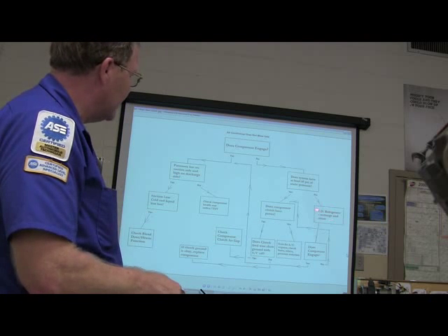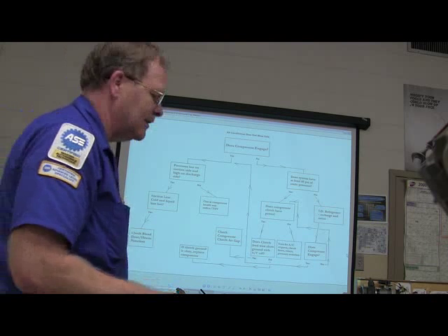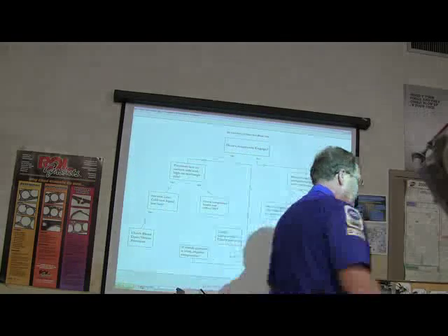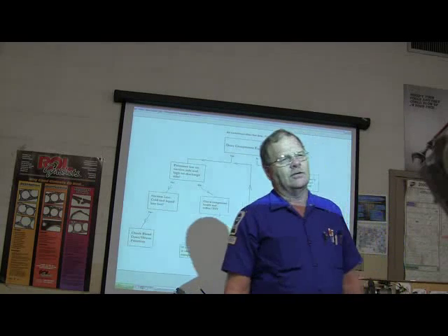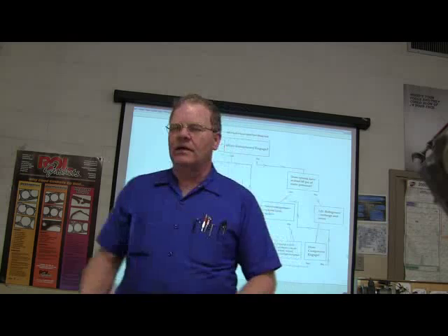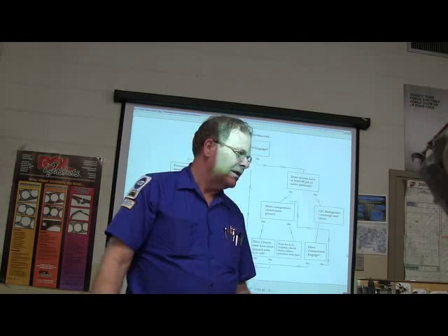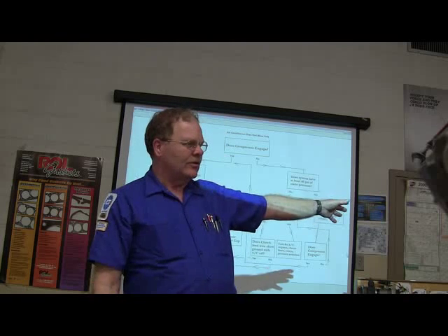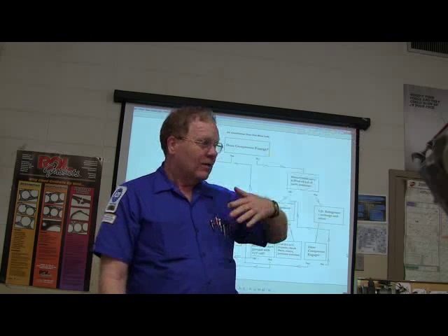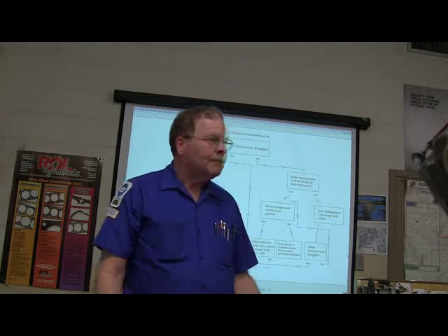Now, identifying the refrigerant is really important. Sometimes I'll see people rolling the big machine over there when they haven't even identified the refrigerant. If you haven't identified the refrigerant, you may pull some kind of trash gas into my machine, and then it's got issues. Because all over the countryside, people don't use the refrigerant identifiers. That's why we need one, because they don't have one.